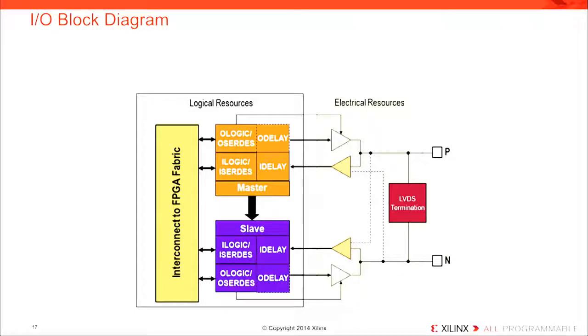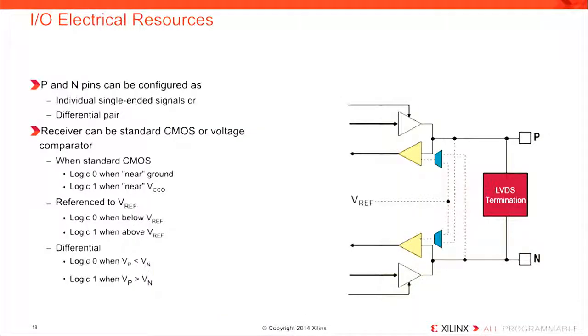All right. So the voltage compensation and the I/O standards are implemented right here. Once that happens, then you move into logical side, and then you do logical operations using logical resources. Right? So, this just shows you that you have pins here and it's going into the fabric, or from fabric is coming back out, right.